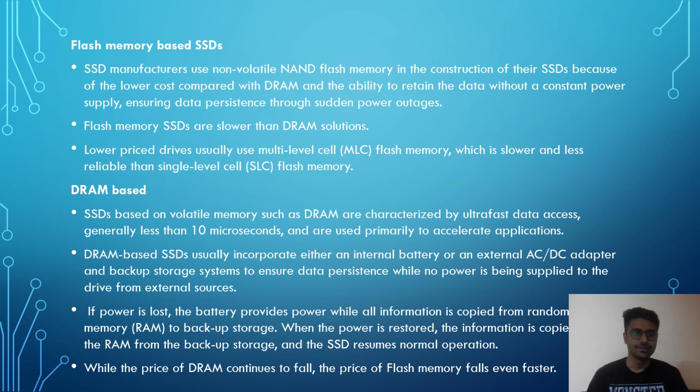DRAM based. SSDs based on volatile memory such as DRAM are characterized by ultra-fast data access, generally less than 10 microseconds, and are used primarily to accelerate applications. DRAM-based SSDs usually incorporate either an internal battery or an external AC/DC adapter and backup storage systems to ensure data persistence while no power is being supplied to the drive from external sources.